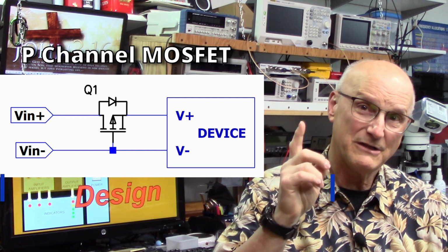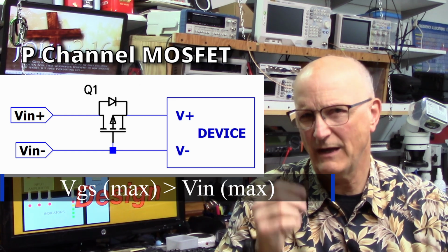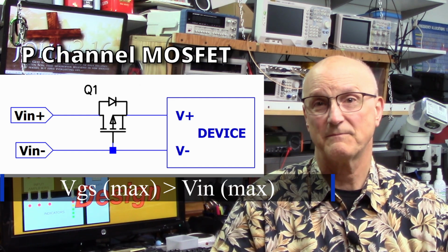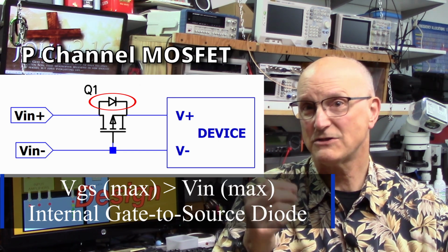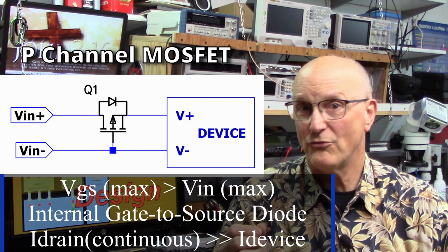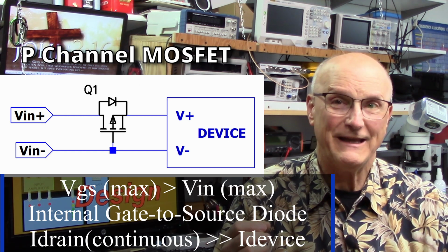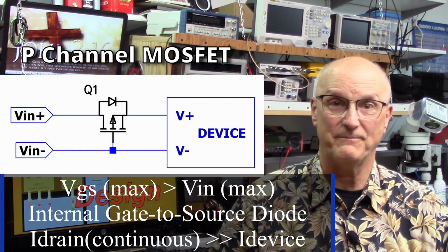Well, you must choose a device whose maximum gate voltage is above the maximum input voltage of the design. It needs to have an internal gate to source diode, and it also has to have a current rating which significantly exceeds the anticipated current that will be drawn by your design.